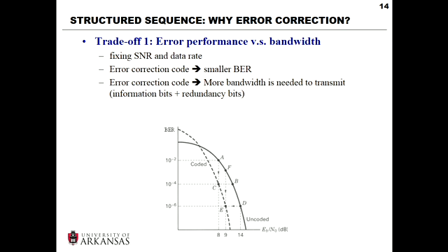We transmit 1 megabit of information per second. If we use a channel code with rate 1/2, in reality we will need to transmit 2 megabits of data in the channel, okay? So in this case, our actual transmission rate is doubled, which means our bandwidth is doubled, right? As we have learned, the bandwidth is proportional to the symbol rate, okay? If we fix the modulation scheme and our symbol rate is doubled, then our bandwidth is doubled.